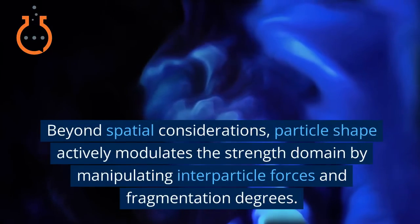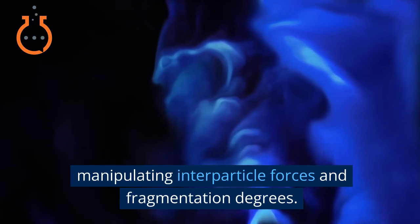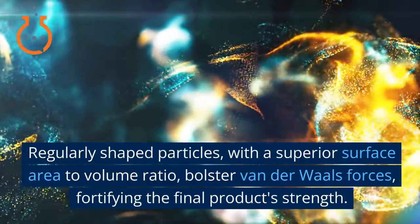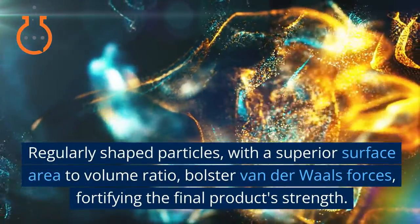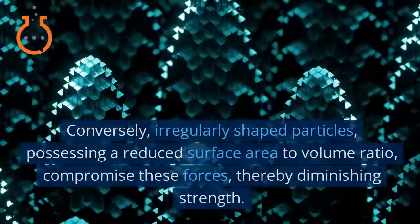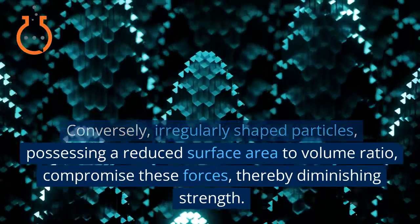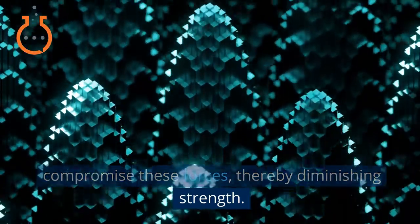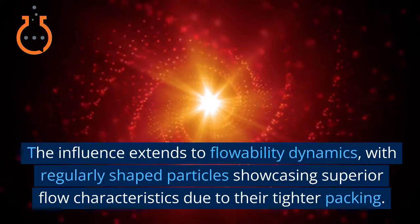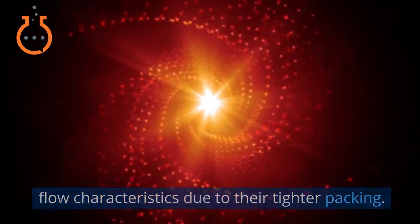Beyond spatial considerations, particle shape actively modulates the strength domain by manipulating interparticle forces and fragmentation degrees. Regularly shaped particles, with a superior surface area to volume ratio, bolster van der Waals forces, fortifying the final product's strength. Conversely, irregularly shaped particles, possessing a reduced surface area to volume ratio, compromise these forces, thereby diminishing strength. The influence extends to flowability dynamics, with regularly shaped particles showcasing superior flow characteristics due to their tighter packing.